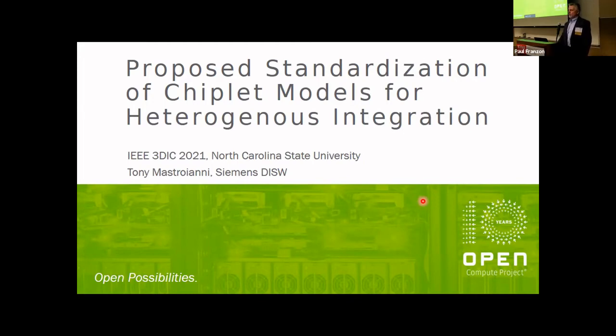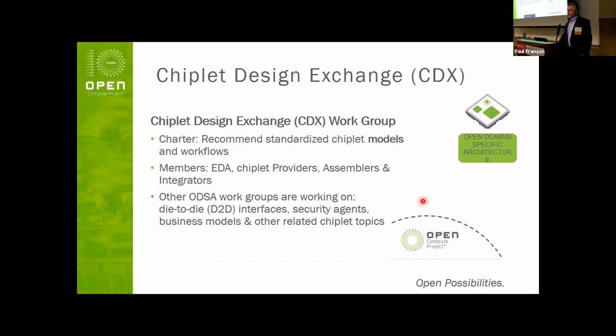This is a proposal for a set of standardized chiplet models to be delivered by chiplet providers to their end users, system integrators. Before I start, I'd like to begin with a brief definition of a chiplet in the context of this paper. The chiplet is an ASIC die specifically designed and optimized for operation within a package in conjunction with other chiplets. This is referred to as heterogeneous integration, where multiple die or chiplets are integrated into a system in package. For the purposes of this paper, we'll focus on the heterogeneous designs implemented on silicon interposers.